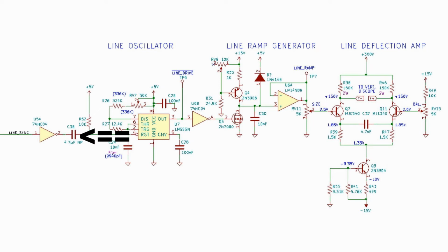The reset pulse here is line sync. This is arriving at 400 Hertz minus the 1 sync pulse used for frame sync. That's the reason for this oscillator, in the sense that if that frame sync pulse doesn't arrive, this oscillator naturally runs at 400 cycles as well, and it will simply oscillate for the 1 missing pulse, producing a continuous train of pulses on its output at pin 3.